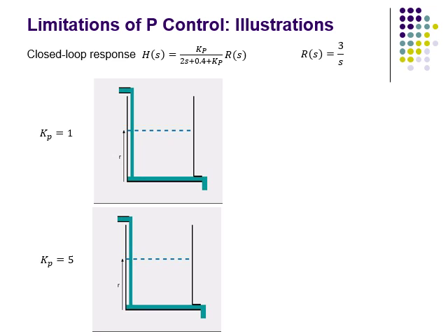Initially the height of fluid is 0, so the tank is initially empty. The initial value of H is 0, and we can calculate the response of the system if the reference value is a constant value of 3 meters. So R is set to 3.